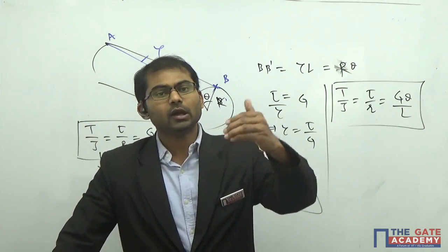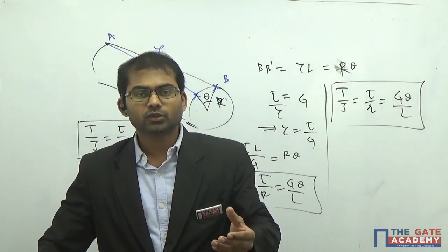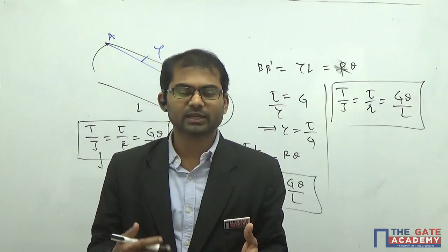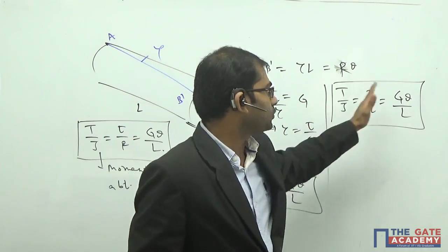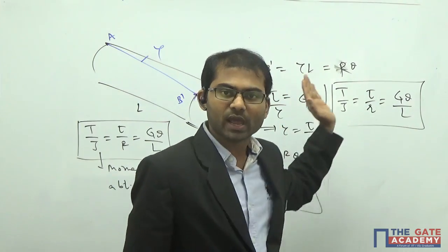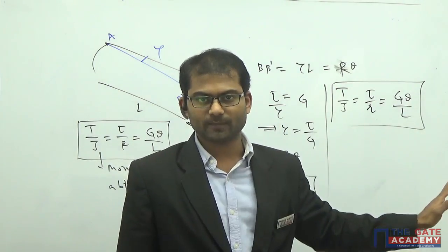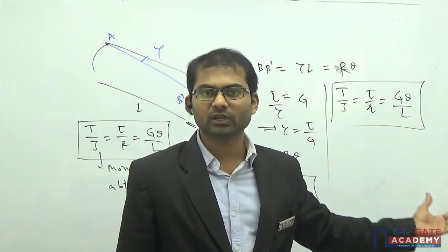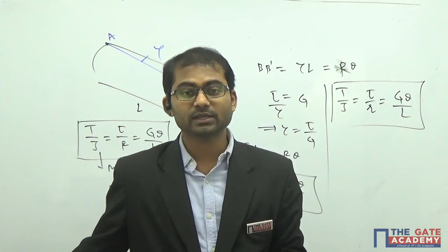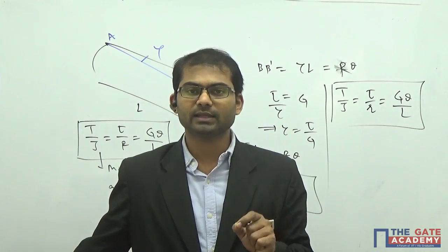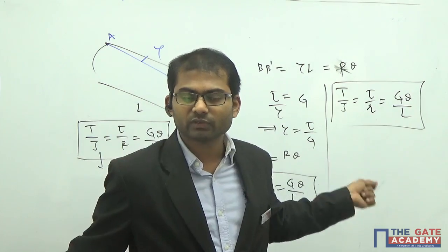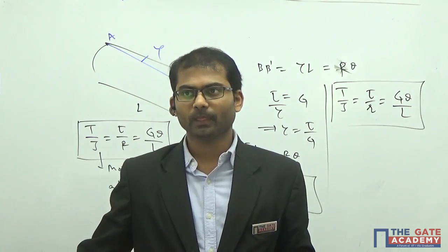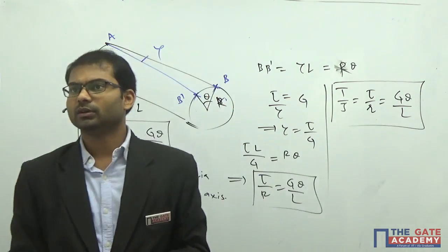They are dependent on the value of torque applied, so torque is the deciding, independent parameter. It gives rise to shear stress tau and angular twist theta. Based upon this definition only, I am going to give you one question in the coming slides. If you don't understand the meaning of this formula correctly, you'll end up getting a wrong answer. Understood? So please copy this one here.